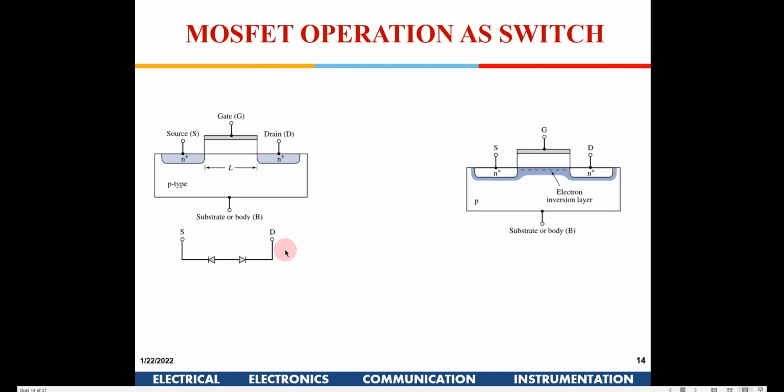Now when we see the MOSFET operation for a digital circuit, what is the voltage a gate can withstand before breakdown? I guess a 40 angstrom gate can handle around 4 volt. Each technology defines how much gate voltage it can withstand.